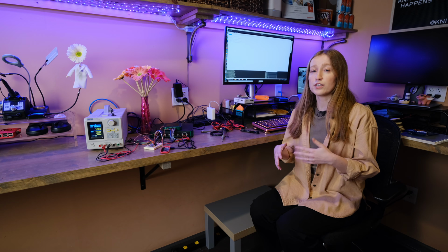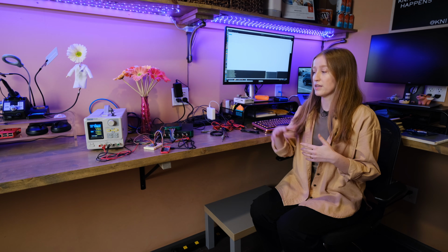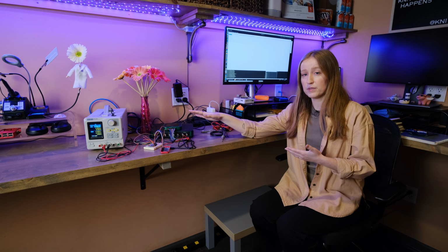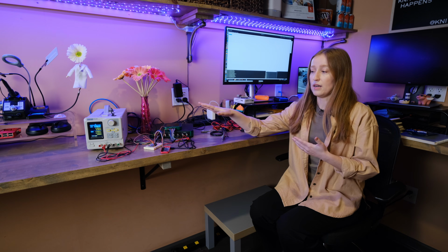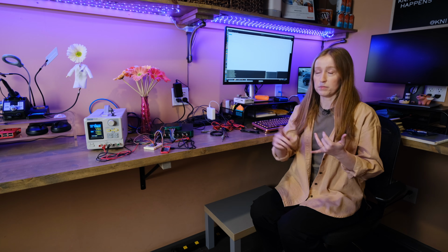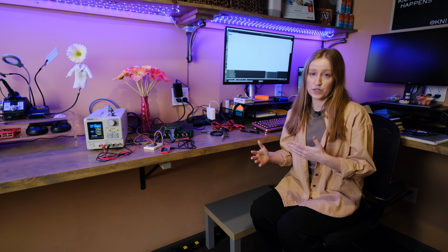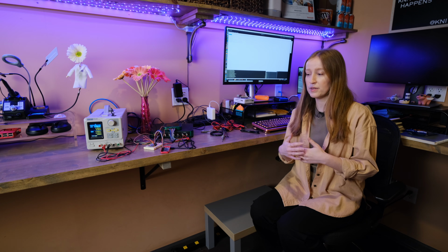So for the software to control your setup remotely, obviously you can do everything piecemeal by using the respective GUIs that come with your USB instruments. You can use just a plain old Python script that sends your SCPI commands straight to the socket, or a lot of modern instruments, like from Keysight or any of the other major brands, have proprietary GUIs that come with them to handle the SCPI commands in the background for you.